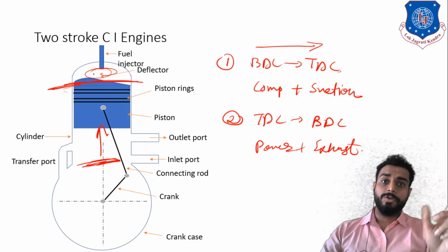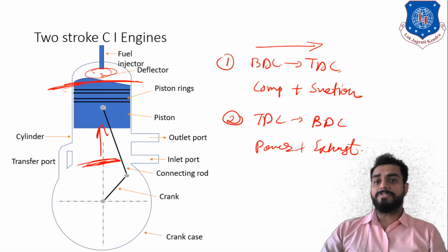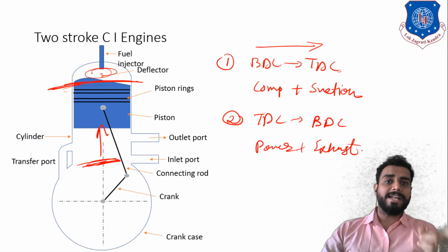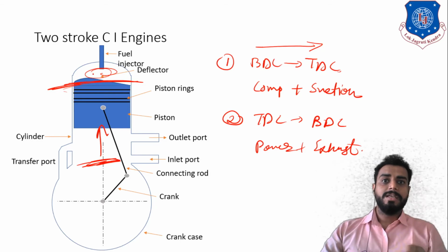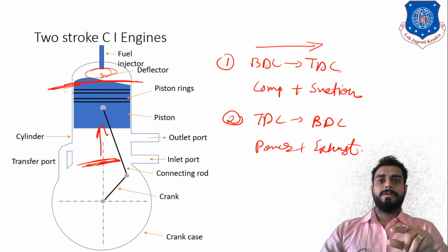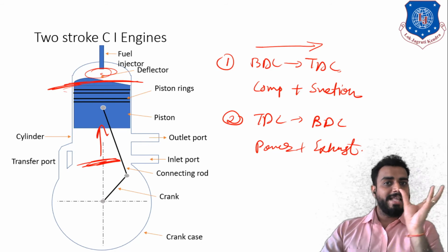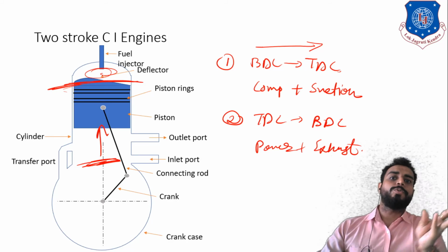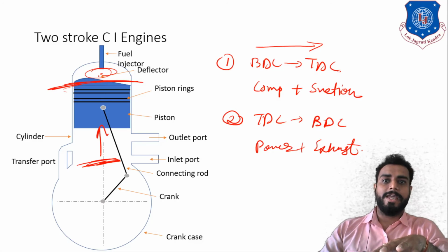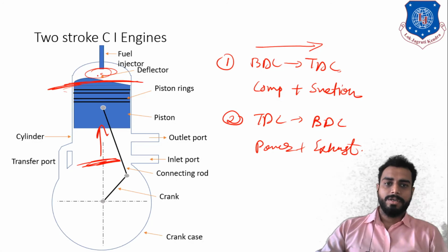Okay, so here no spark is produced to ignite the fuel. That is why these particular engines are called compression ignition engines, because ignition occurs due to self ignition. Self ignition has occurred due to the already compressed air. When you compress the air, its pressure and temperature will increase, and that increased temperature is equivalent to the self ignition temperature of the fuel. So as soon as you enter the fuel in the self ignition area, the fuel will ignite itself. Okay, so that's how it works, right?